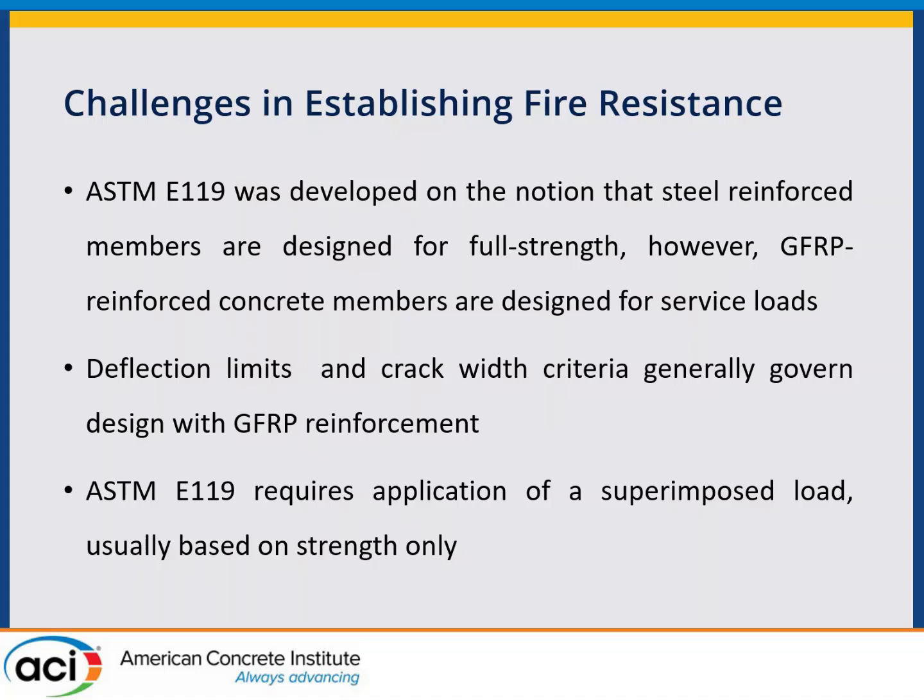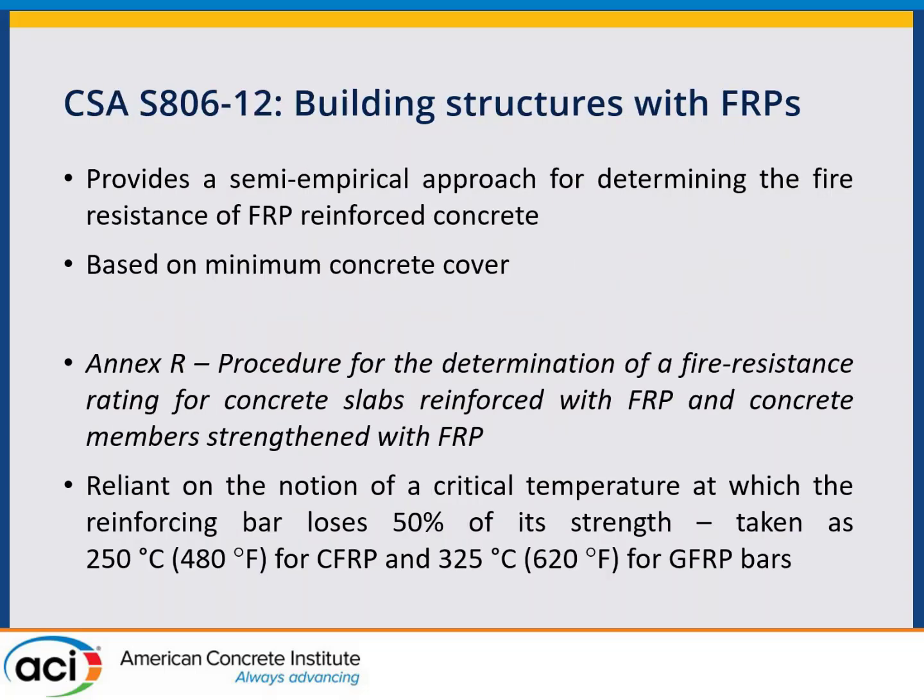We don't have those types of restrictions on steel. You might easily have 60% of the strength or more in a structure under its regular loads. So this is a challenge with the fire testing community, in that it's all based on those assumptions for steel, which don't apply for GFRP reinforcement in concrete because of the different behavior of the materials.